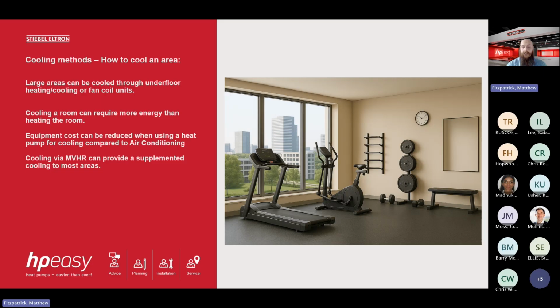This is what I would class as a supplementary heating or cooling method. If you had cooling through underfloor with cooling through the MVHR, you will see a better benefit rather than just cooling through the MVHR on its own.